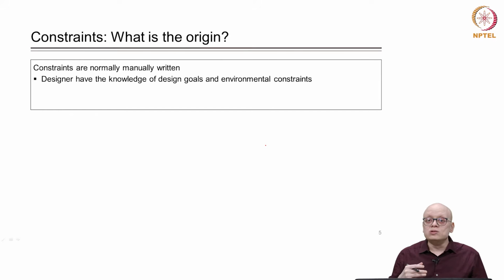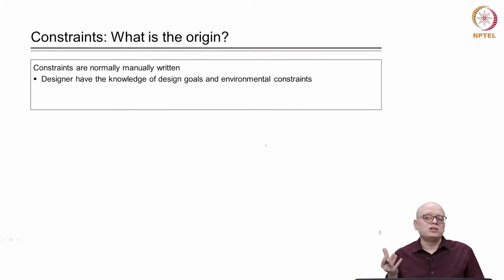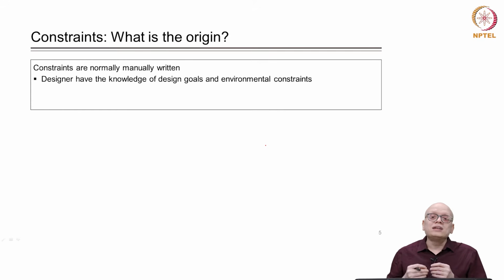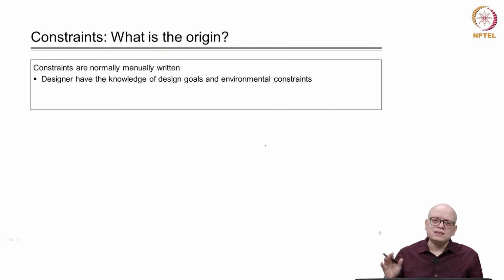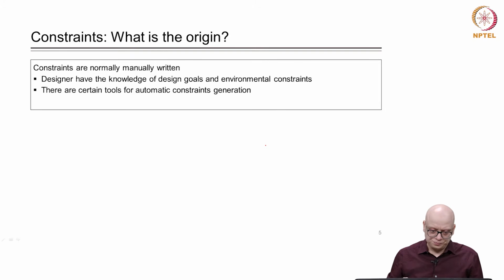So the constraints file needs to be written by the designer, because the information in the constraints file is not available in the design, or it may be very difficult to derive in some situations about the functionality. Though it may be derivable, that may be very difficult, and therefore we do not give the tool the responsibility of deriving those things, but provide those constraints as a designer by manually writing the SDC file. What that information is, we will see in the subsequent slides.